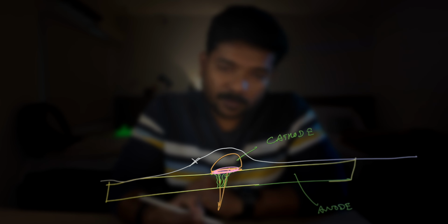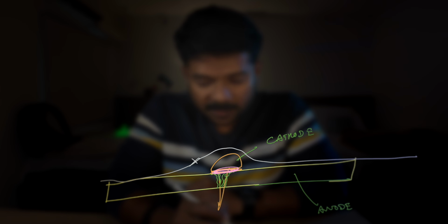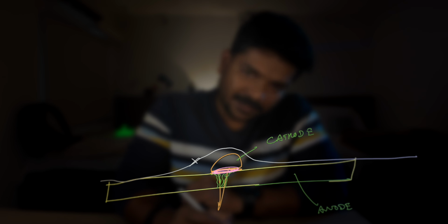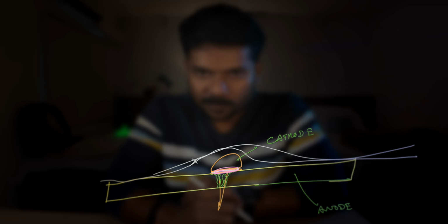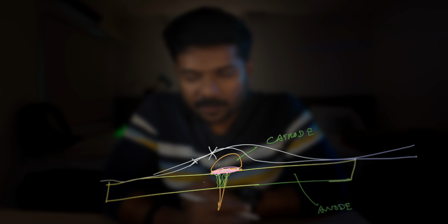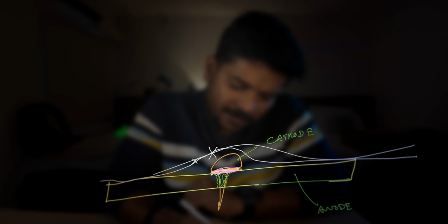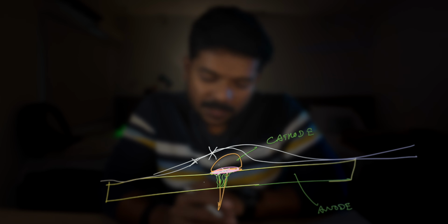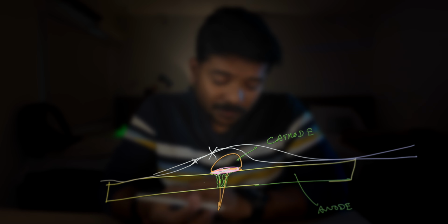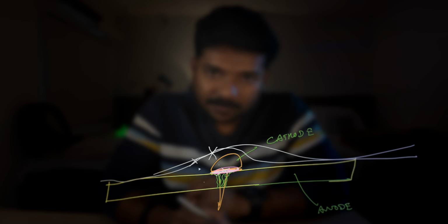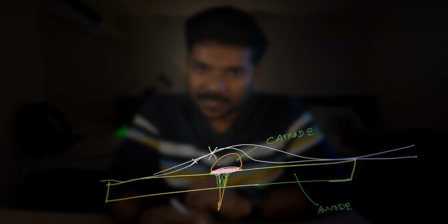So what happens is, if the waterproofing membrane fails, there is a washer that can prevent corrosion. If you miss out the washer, there is a waterproofing membrane that could prevent corrosion. And if both of these fail, the metals used are not too far apart from each other, and the rate of corrosion will be slower. Well, now it remains on the quality control. The quality control should catch that something is missed out or something is damaged and should be rectified.